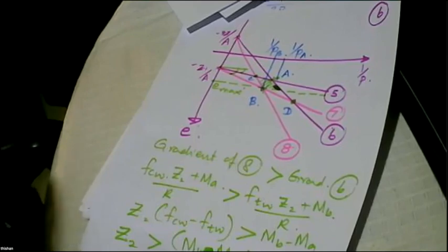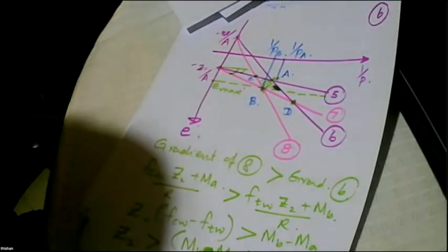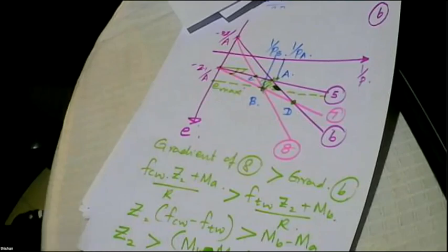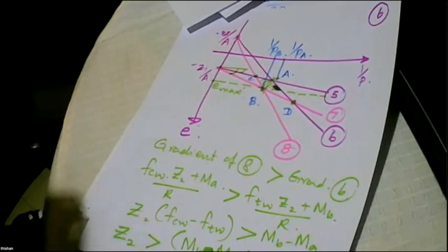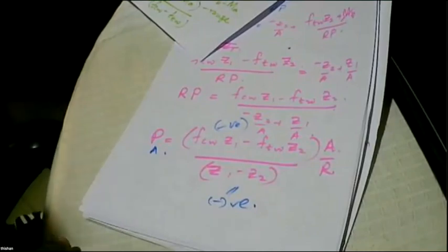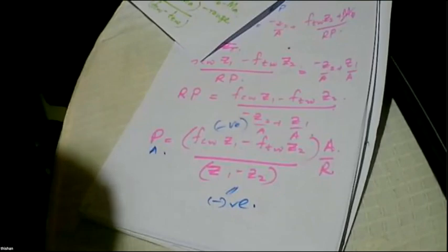And it looks like the equations for a continuous beam appear pretty much simpler than the simply supported case, because in the simply supported case, at transfer the pre-stress was P, under service RP. So R term would be seen in the equations, but here, R term is not very important, and it appears, but for PA and PB, R term will come. And here you can see it depends on the allowable stresses and the section sizes, it is not based on the bending moment. So those are some of the pretty interesting things.